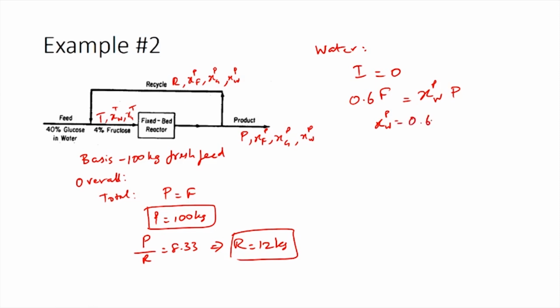So, now the next step is for us to get information about the mass fractions of the product streams, recycle streams and the gross feed. For finding this information we need to choose an appropriate system. If we were to choose the splitter, we would be able to write only one independent balance equation. Hence, it would not help us in identifying all the unknowns.